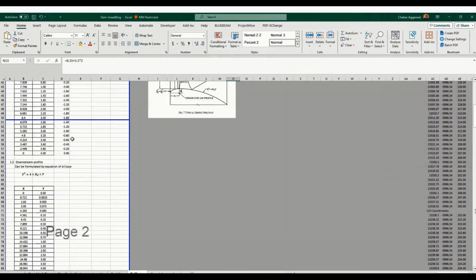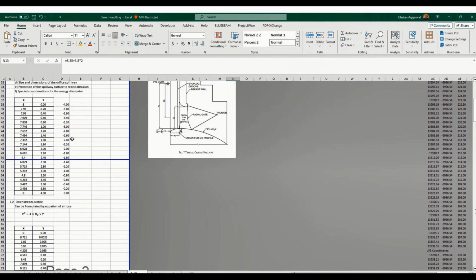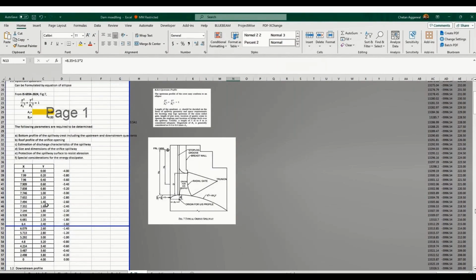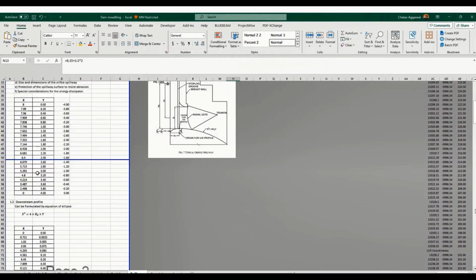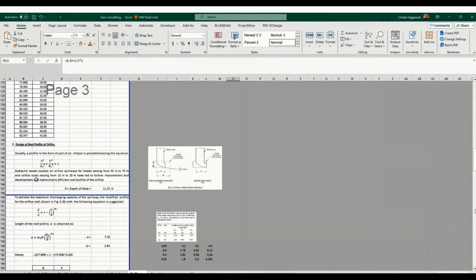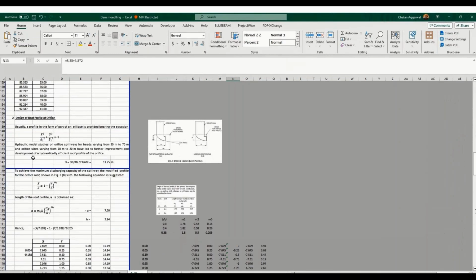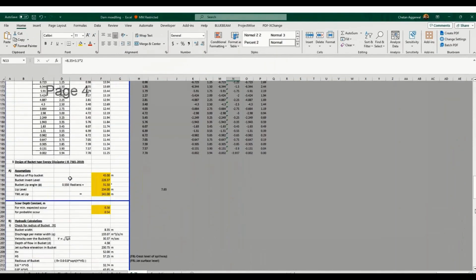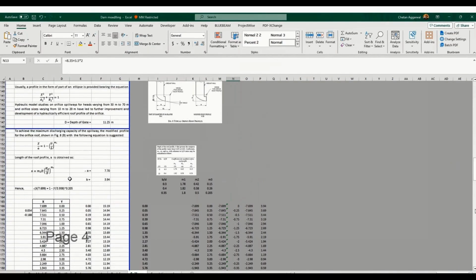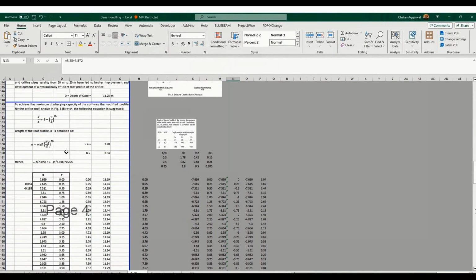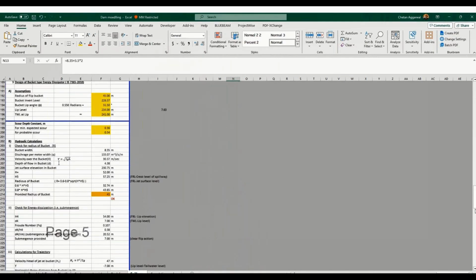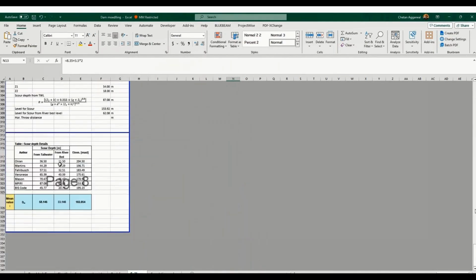So we have these crest profile, upstream crest profile, downstream crest profile, and this breast wall profile also. The piers will be quite high here, so it's always better to have a radial gate with the breast wall if the pier height is say more than 10, 12 meters, 15 meters. Okay, and then we have a bucket.